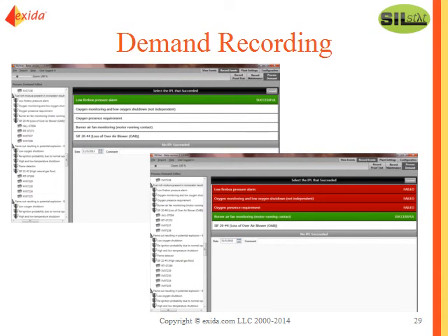In the second example, I'm listing that the burner air fan monitoring motor running contact was successful, which means in this example that these 3 layers of protection failed. So I automatically record their failure. That leads to maintenance activity, and I need to look into why these failed. But in both cases, I may have had 2 hazard scenarios. The overall demand of the process is at a certain rate, but in both cases the safety instrumented function was never exercised. That's something you can keep track of, and the tool will automatically determine.